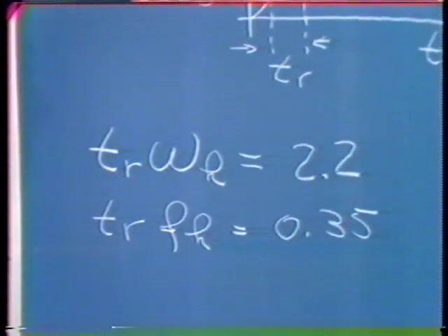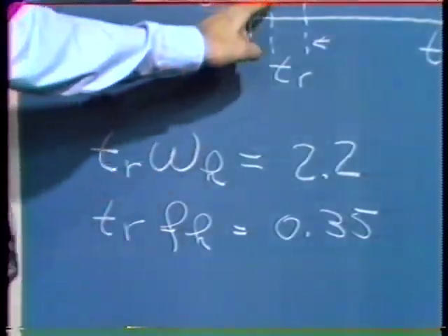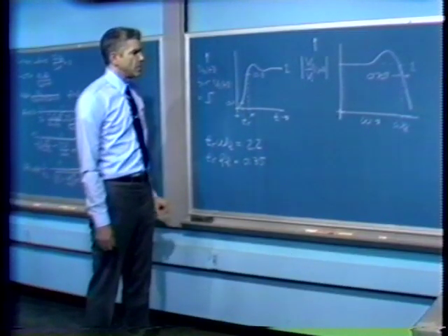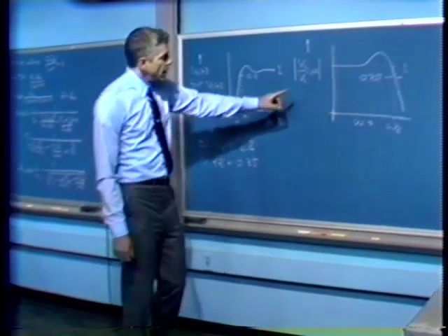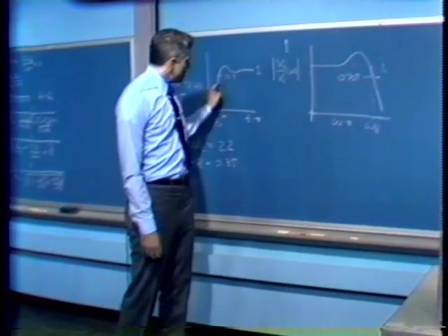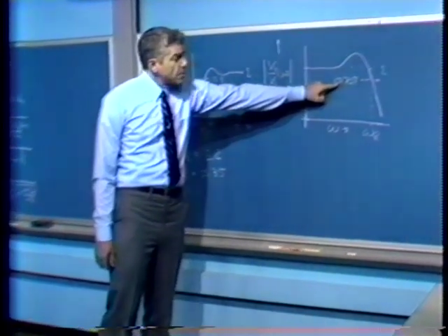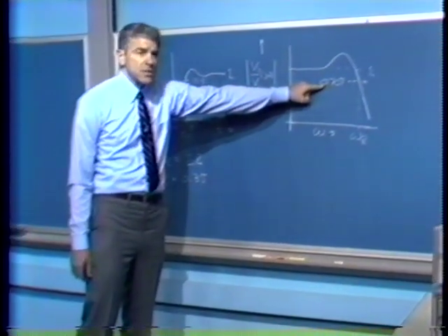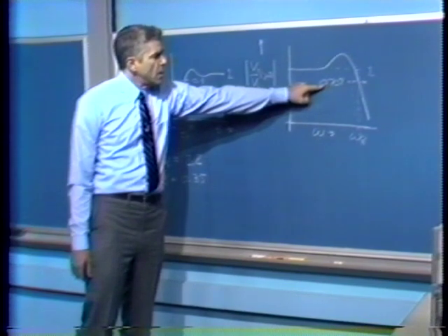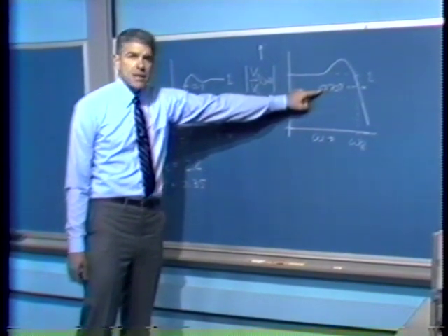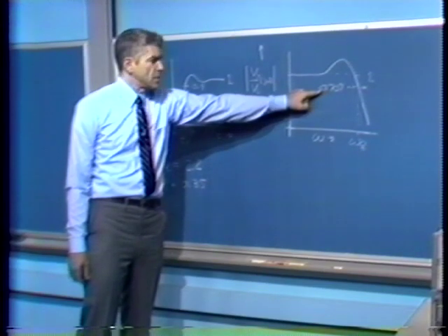Again, what this does is allow us, for example, to make a simple, experimentally simple step response measurement, and by using information on the rise time, estimate what omega h, what the frequency response of the system, will be. And that gives us a much more convenient way of estimating the frequency response than actually making the detailed measurement, which is experimentally cumbersome.